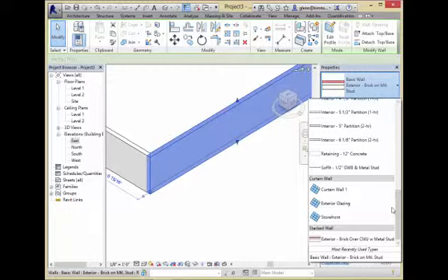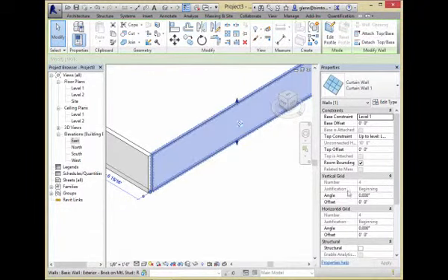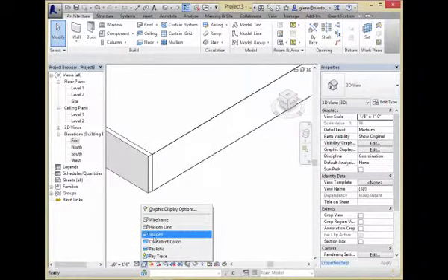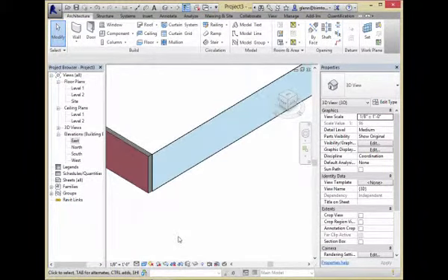Actually, it's just a curtain wall with different parameters sort of specifying the pattern a little bit differently. But they vary from, if you choose the curtain wall 1 type, it's a big old blank sheet of glass. Let me change that to colored so you can sort of see that. So give it a little bit of color so you can sort of spot it. It's a big old sheet of glass, which is an okay starting point for the design. You aren't probably going to build it that way because 20-foot tall, 80-foot long pieces of glass are hard to come by and expensive and dangerous and all that kind of stuff. So, that's just kind of a starting point.